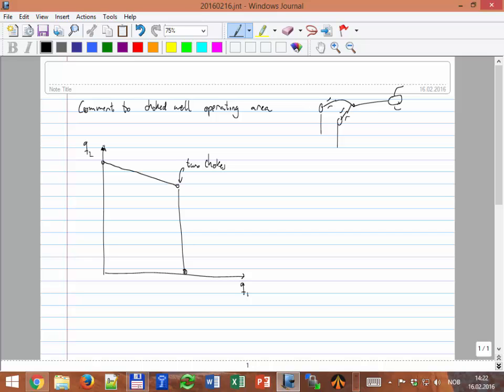One person was asking that when do I get the maximum production? Okay, optimization. So when do I get, in this system, maybe there is a choke opening. Okay, I think that maybe trivial. Okay, the 2 chokes open, that's the maximum production. But maybe I find there is a particular setting, let's say this choke 30% and this choke 50%, that gives you maximum production. So how can I see that from this plot?